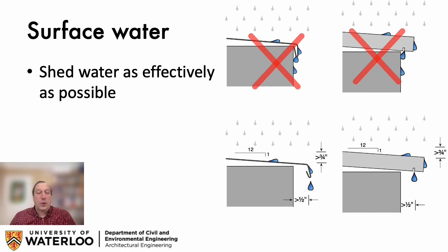Now, with windowsills, or parapets on roof, coping on a roof parapet, or any kind of horizontal surface that then intersects with the wall, we are working also on shedding the water. It's not just at the eyebrow of a window. We use metal, as shown here in this left-hand side example, and often what's called hem the edge, H-E-M.